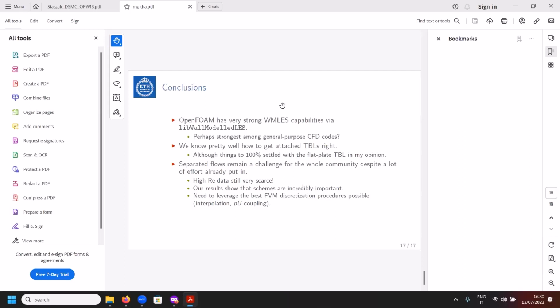Yeah. Well, so there's always the problem with this coupling between the unsteady solution you sample and put into the wall model, and the fact that the wall model is essentially written for a mean flow, right? Yeah, somehow either you just say, okay, I'm just going to use a transient signal, or sometimes you average the signal to make it more compatible with the wall model. But in principle, the issue remains. You are using an average equation, or some people just use full-blown RANS equations for the wall model. But still, it's for an average flow. So there's no way around it.